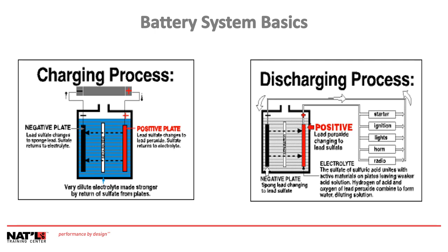In the reverse process, a battery becomes charged when current flows back into it, restoring the chemical difference between the plates. This happens when you're driving without any accessories and the alternator puts the current back into the battery. As a battery discharges, the lead plates become more chemically alike. The acid will become weaker and the voltage will drop. This is the interrelation between the three. Eventually, the battery is so discharged that it can no longer deliver electricity at a useful voltage.